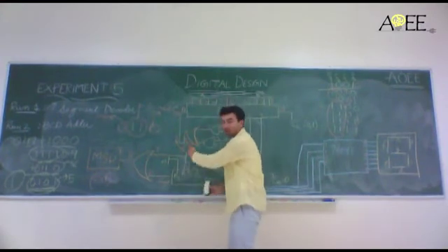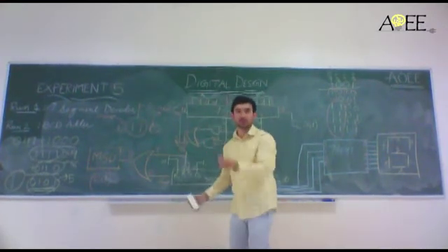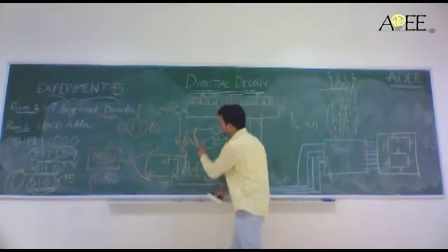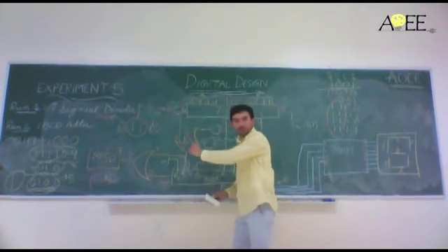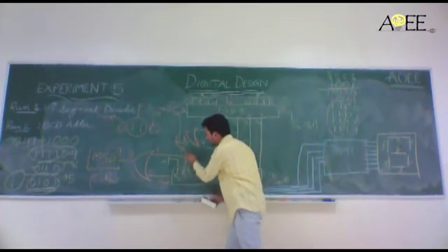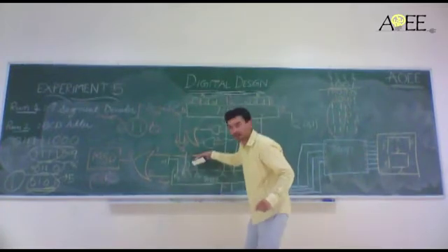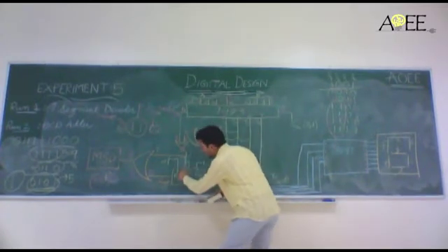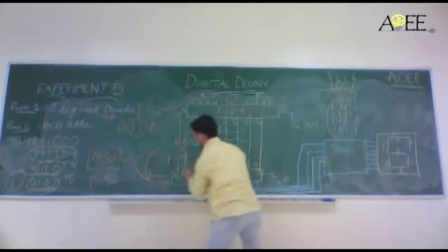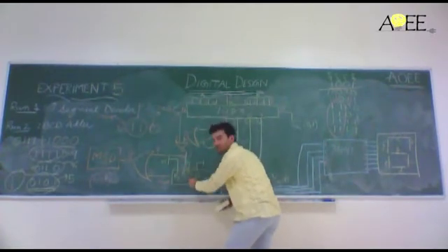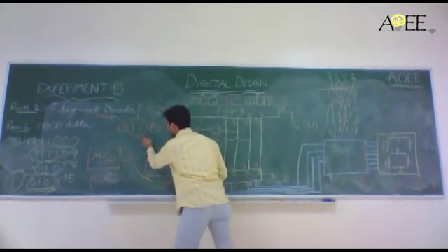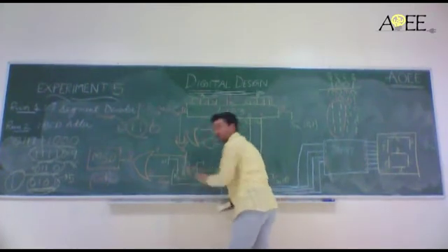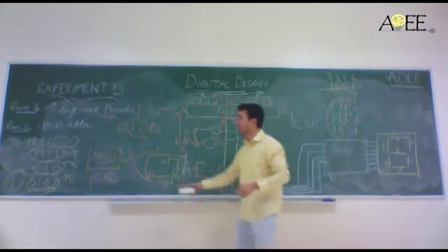We used 2 input ORs, so that's why 2 ORs, otherwise a 3 input OR can be used for all three. So if any one of them exists, then I have 1 coming out. If 1 comes out, then what do you do? Make this ground and make these two 1. So this will give me 6. So 6 is one of the inputs that has to be added. We had to add 6.